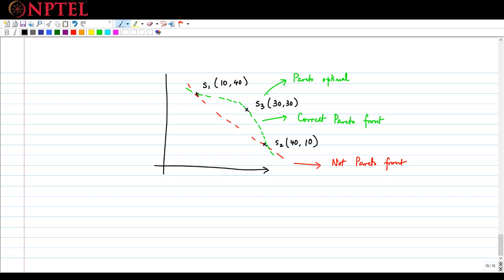The bottom line over here is that more complex gates in general are likely to have higher capacitance, right? So you can assume that a 3-input NAND gate, for example, will have a higher capacitance than an inverter, right?